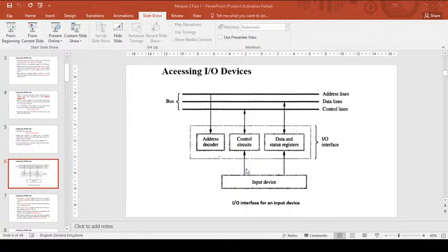And then we have something called DIRQ and KIRQ. These are used for interrupts. Interrupts is the next concept which we will be studying under this chapter. For the time being, we will not discuss that. Then in the control register, which is again an 8-bit register, we have DEN and KEN. These are again enable flags which are used for interrupts.